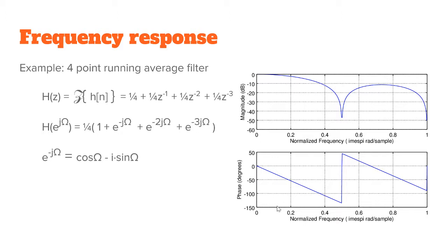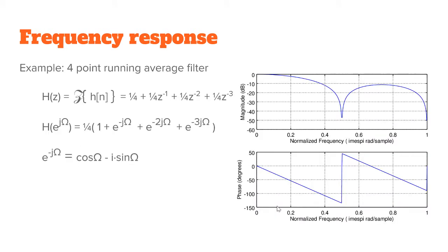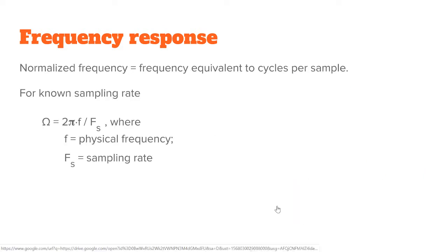Yeah, and then we have this phase response. Okay, that's interesting. Actually, the phase response is quite linear. Well, on that point, it's a special point. So basically, it's undefined at that point, and then it jumps again there. But anyways, it's continuously linear. There is a special meaning for the linear phase response. But first, about that frequency, yes, this omega is the normalized frequency.